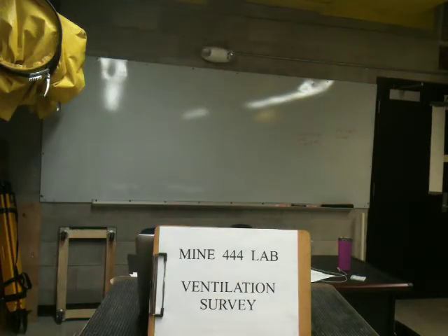This is normally something that we would have you guys doing as a lab exercise. You would have two people holding pitot tubes, just holding them, and we'd record the delta pressure measurements. But in this day of social distancing and hand sanitizing, it's just going to be me using the tripods. Okay? So we're going to go around the airway in the direction of the air facing into the airflow. We'll record the delta total pressure values as we go around, and then finally we'll measure the pressure increase across the fans. So I'm going to take the camera off and show you the setup here.